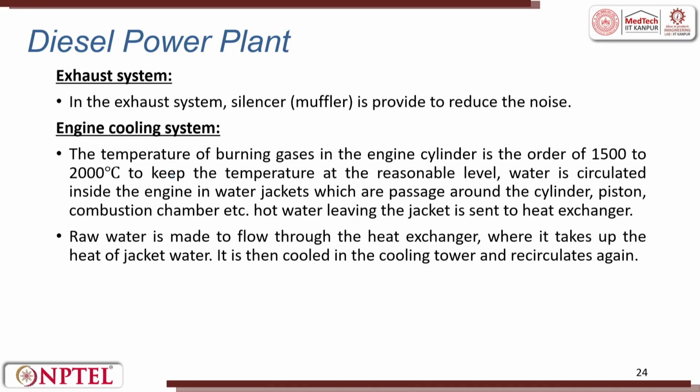Engine cooling system. The temperature of the burning gas in the engine cylinder is of the order of 1500 to 2000 degrees Celsius. To keep the temperature at a reasonable level, the water is circulated inside the engine in the water jacket, which is passed around the cylinder, piston, combustion chamber, etc. The hot water leaves the jacket and is sent to the heat exchanger. You can reuse the water.